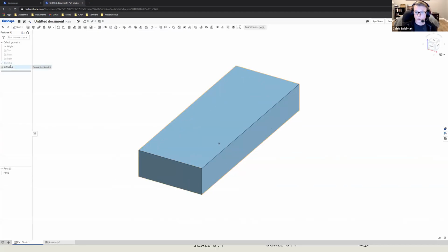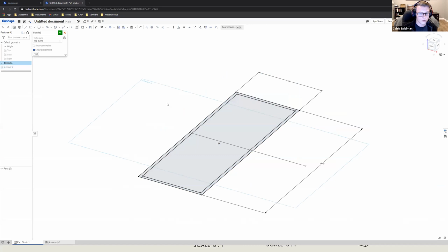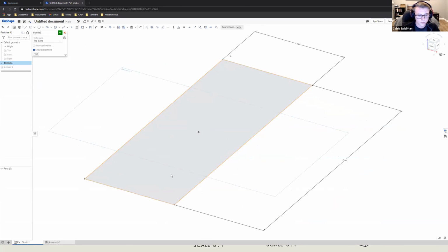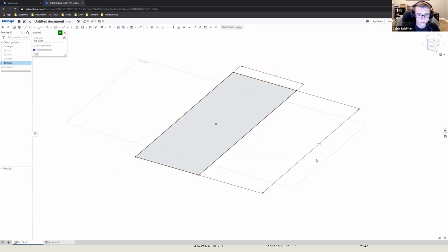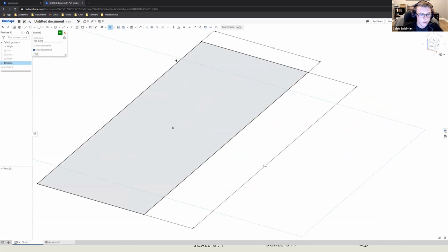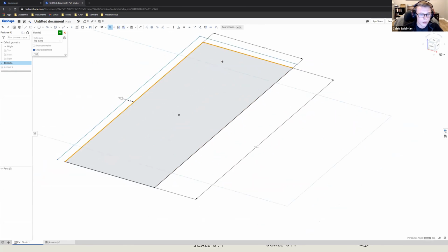You can either do a cut feature, or you can just go into the sketch, and you see what I did here with the offset. I'll show you how to do it again. Oh, apparently I can't delete that. All right, there we go. In the menu selection bar, I have this offset tool. It looks like a boot. It's very strange. I can now highlight the sketch entities that I want the offset to be on, and you can see what the offset does on my screen.